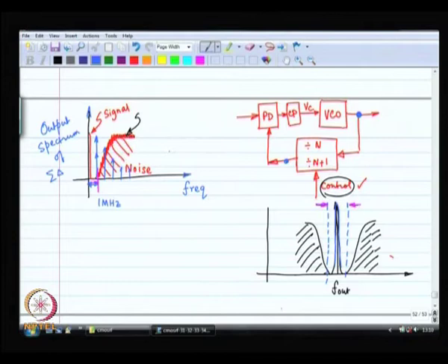So, from 0 to 1 megahertz you have to make sure that there is only signal and no quantization noise. So, now you have to make a more intelligent design for the sigma delta modulator, so that no noise is produced in that region. So, you have to place zeros, for example, you have to make a higher order sigma delta modulator, so that the quantization noise is so many decibels, 100 decibels below the signal or something like that, right. So, all of this depends on what your phase noise requirements are. Now, it is really getting interlinked.